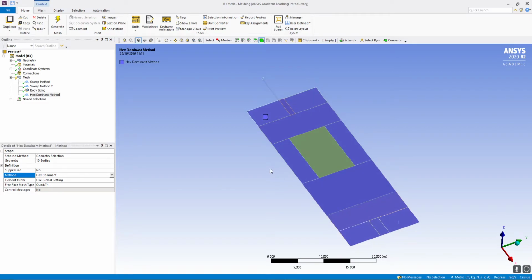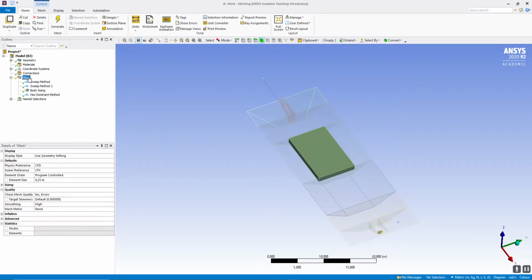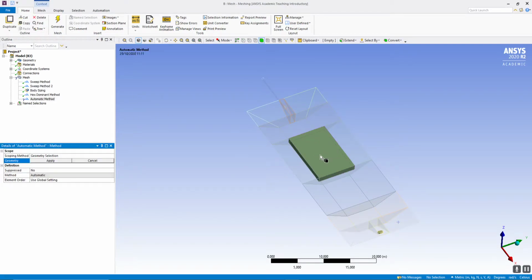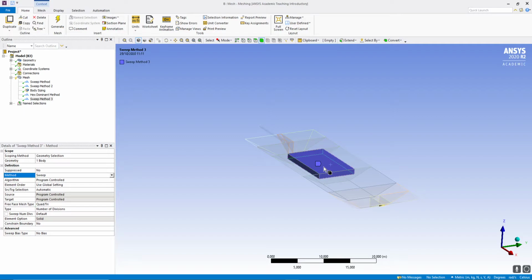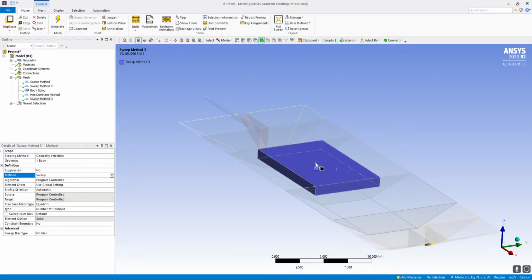Very well. Now we will create our fourth and final method, that is the one that we use to represent the vegetation. For the vegetation, we're also going to use the sweep method, all right? For the vegetation, you don't need to use the screen target because the faces are exactly the same, so using either of them will be fine, all right? But we are also going to improve some stuff in this mesh for this geometry. Let me give you an example.